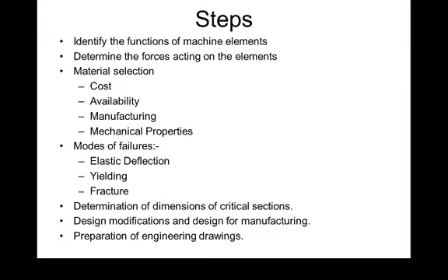What are the design steps? Design is classified into four to five major steps. First of all, we have to design and define the function. What is the usefulness of the product? Then we have to go for determination or calculation of the stresses, what forces will come, what strengths will come. Everything has to be validated. Then the next one is material selection. This is the most important step.